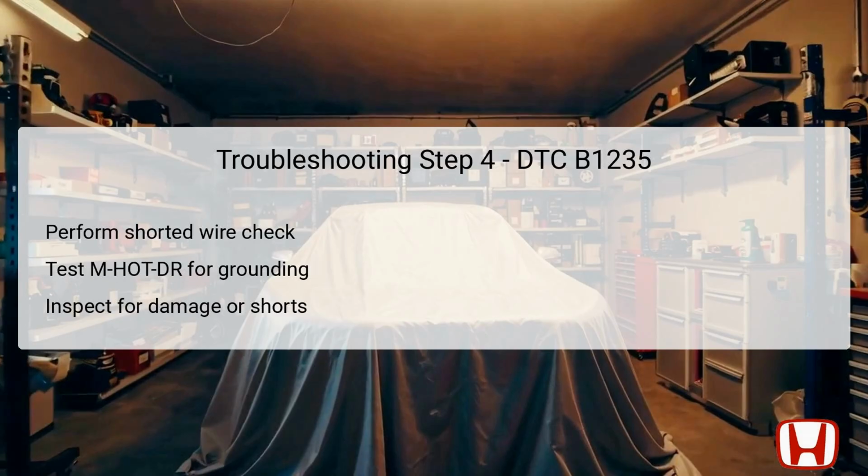In this fourth troubleshooting step, the focus shifts to checking for potential shorted wires within the MHOT DR line. Keeping the climate control unit connector B24P and driver's air mix control motor 5P connector disconnected. Again, verify the continuity between the specified test points. Test point 1 is climate control unit connector B number 13, while test point 2 is a body ground connection.